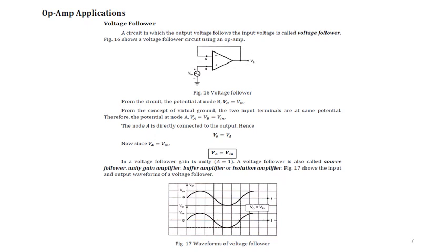And the last circuit we'll discuss is the comparator. The comparator means it will compare the 2 voltages given to the inverting terminal and non-inverting terminal. Based on that, your sine wave will be converted to a rectangular wave or a square wave. These are all the applications we'll discuss. Then we'll discuss some problems related to op-amp parameters and op-amp applications.